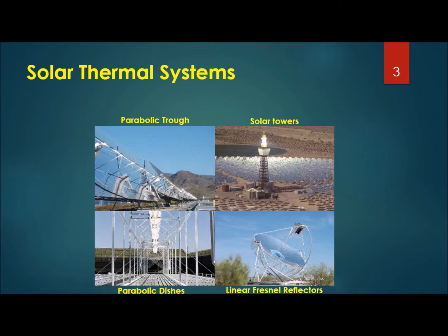This fluid or gas is then used to generate electricity in a small piston or Stirling engine or a micro turbine. Dish technology produces a relatively small amount of electricity compared to other CSP technologies, typically in the range of 10 to 25 kilowatt, which results in high capital cost.